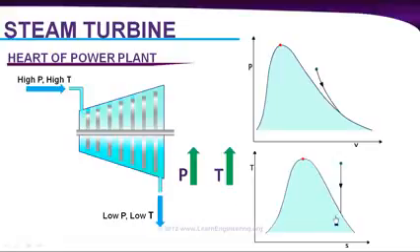Instead, if you can convert this fluid into liquid state, then the compression will require very little energy, or it's easier to compress. So before increasing the pressure, we'll convert this steam into liquid state. For that, what you have to do is reject some heat to the surroundings.